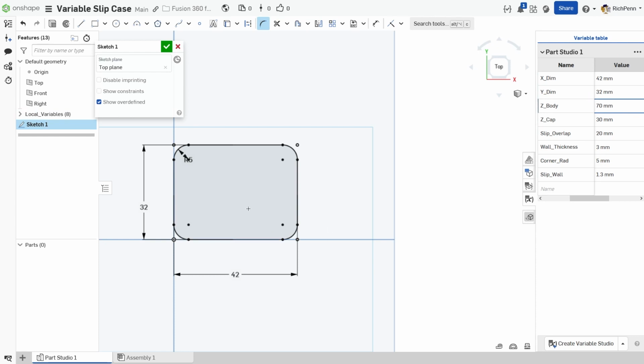This is half of the part. We need to make a second half of the part, and we could sketch it and go through it, or we can simply mirror the part. And the easy way is go to the line tool and then construction, and simply draw a vertical line of any given length